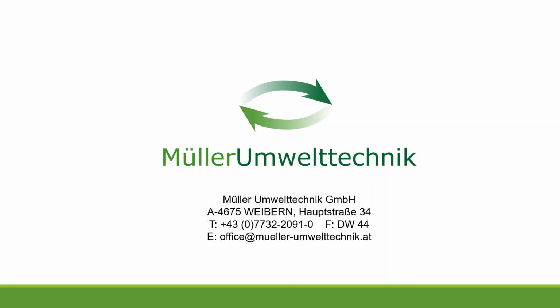So this is the problem we have also in composting. What we are doing is we don't move the substrate in the digester. That means we are taking the substrate as it is into the digester, and there it stays for 3 to 4 weeks. Afterwards, it's taken out, and then we go to a composting area to do the mature composting. And at the end of the composting, we have less humidity, and we are able to screen the compost and to separate impurities like plastics, also metals, and so on.